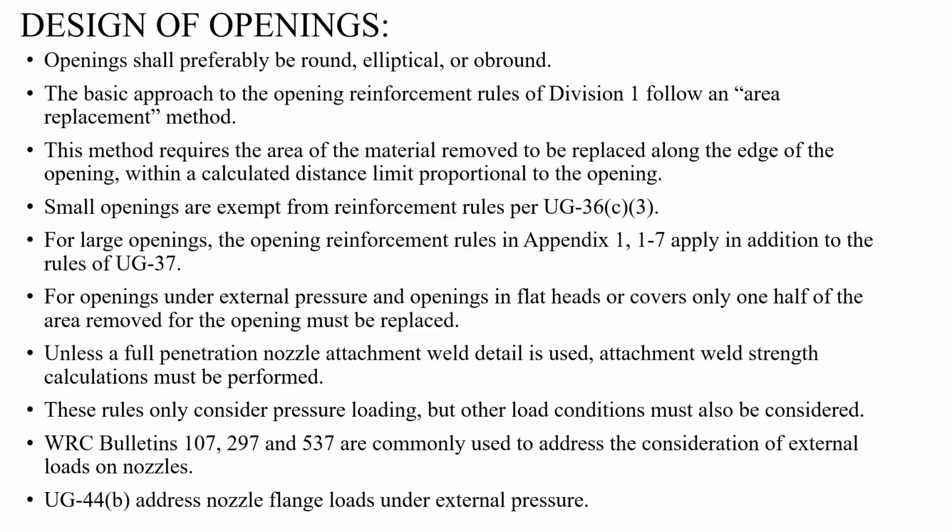So before that, I put a slide which is called design of opening. Design of opening means when you put an opening in a shell or in a head or in any pressure vessel part, in that case you need to follow some criteria to design the opening. The opening shall preferably be round, elliptical, or oblong. So all three are possible.